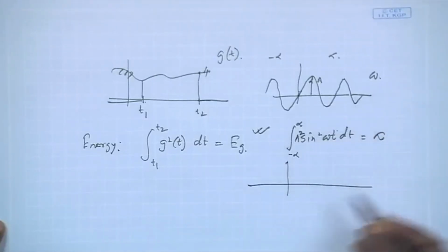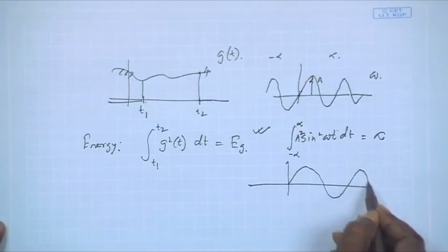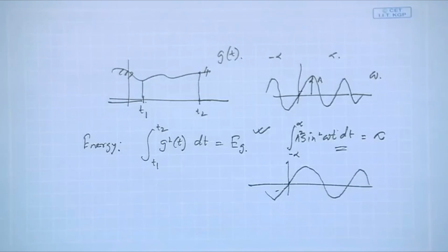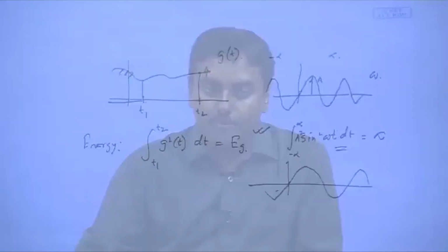Then I have failed to characterize this because it has infinite energy. For any sinusoidal I draw, suppose I draw it with some other omega, so it will have a different frequency, and again I try to characterize it, it will just have infinite energy again. So basically I have failed to characterize the signal with respect to that particular parameter that I have defined, that is energy. Can we do something else? Can we put another measurement parameter which will characterize this signal? That is called power.